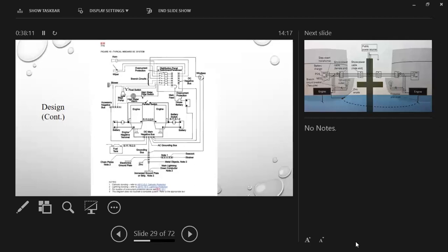You've got a zinc, which hopefully they're going to start calling anodes instead of zincs, because we're seeing fewer and fewer zinc anodes all the time. You've got an anode here wired to your grounding bus, and your cocks, your strainers, chain plates, everything's tied in. Good bonding system, like ABYC likes to see.